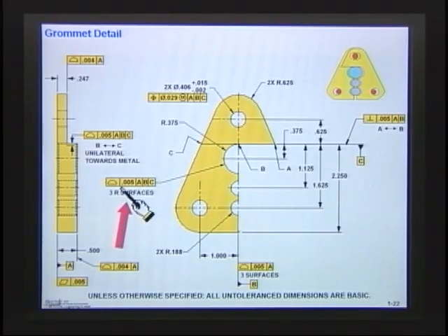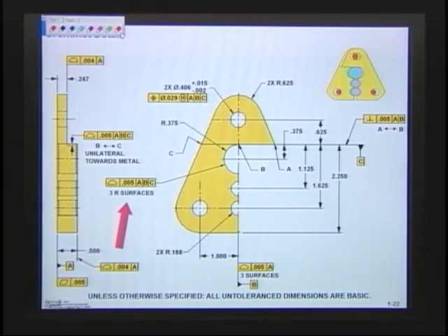As a matter of fact, if you think about it, that's really what I want anyway. When the next part comes together here and that cable fits in, what I'm interested in is what's the smallest that thing can be and what's the largest that thing can be. You see what that is? It's really nice. It's a profile tolerance. It says that radius will be a 375 radius, and then it can come in by 2.5 and can come out by 2.5. And right there I can tell you what kind of squeeze I have on that cable, anything else.